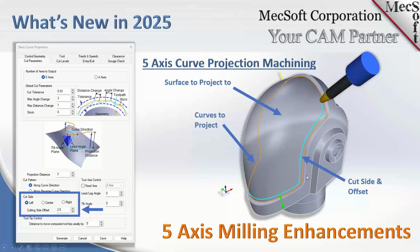And this method is used on 5-axis applications where you want to trim material from the edges of the part, or you want to clean up material on the edge of a feature in 5-axis. So again, this is in 5-axis curve projection, and this is in our premium 5-axis configuration, where you have all of the 5-axis continuous toolpaths available to you. And this one applies to the curve projection machining operation type.